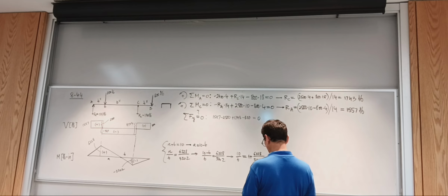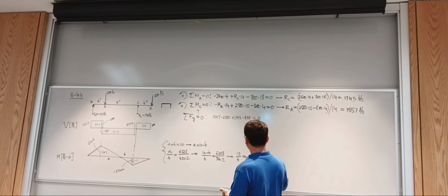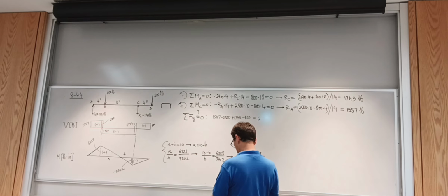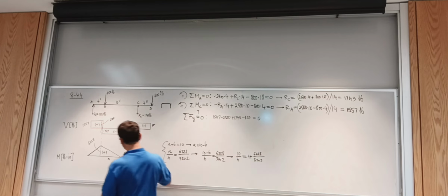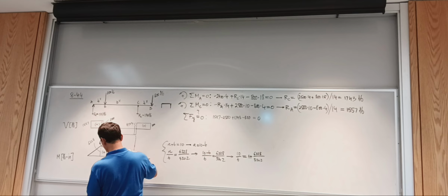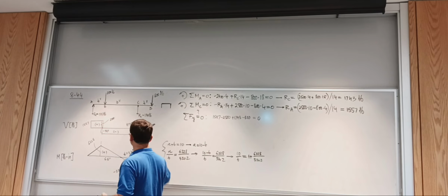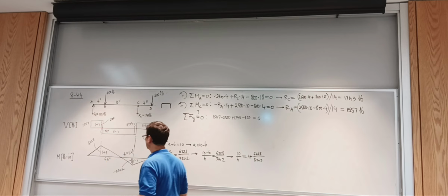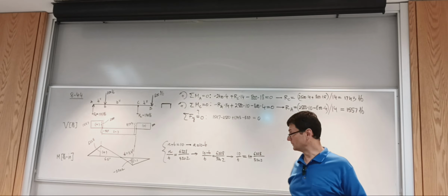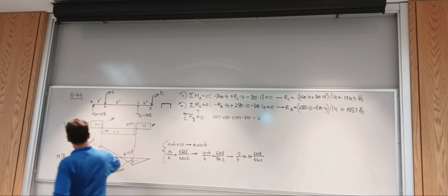6228 over 3202 plus 1 equals, I have this business, and I take the inverse 1 over x and times 10, and it gets me B. So B is 3.3955, we can say easily 3.4 inches. And this other one is the difference, will be 6.6 inches. I said inches. Okay. Anyway, so we can tell the maximum moment. It's this one here. This is M max.